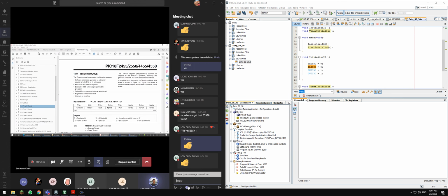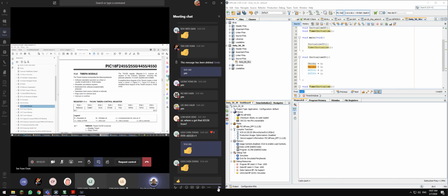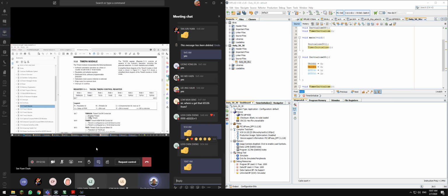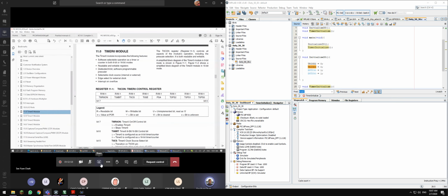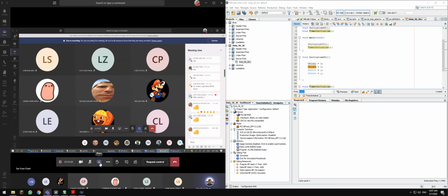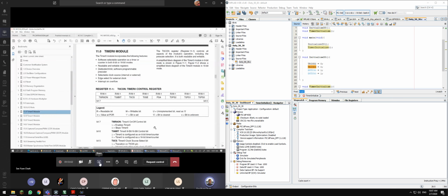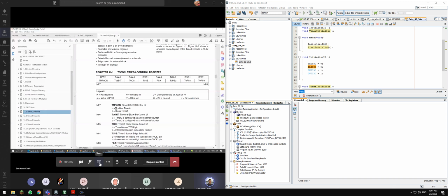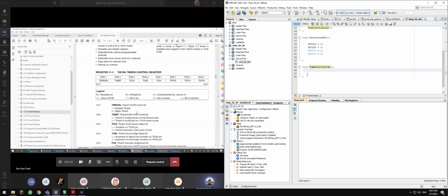Come back to this timer control register. Let's go through it one by one. Is everything okay? Any questions? I hope it's going smoothly. Okay, Timer 0. This one is to start the timer. You start the timer towards the end of the program. Remember, once the timer is started, it starts ticking and calculating. Normally, we start at the end of the timer config.